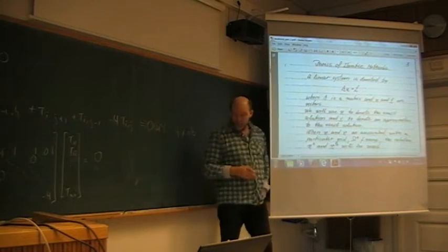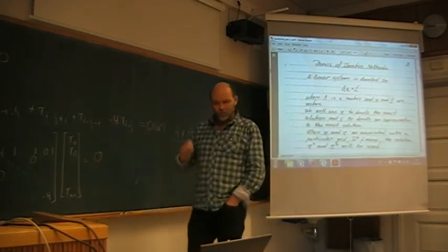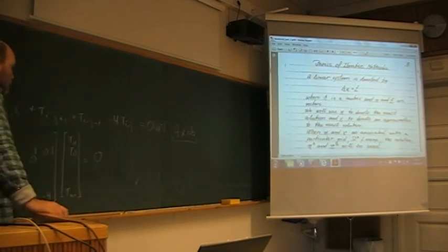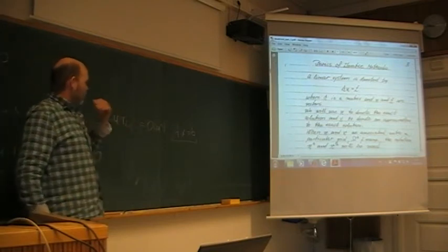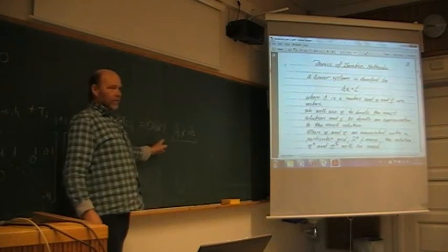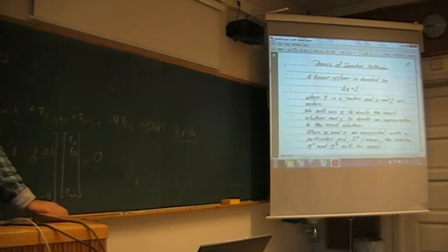It's second order accurate, or depending on your scheme, some accuracy level here. Of course, it's possible now to take this algebraic equation system and solve it perfectly, down to machine accuracy. Yes, you can do that. But why should you? Because you have an error here anyway. So when you have an error which is a little bit smaller than this error, then you should be satisfied. It doesn't help to go any further. So to solve the equation system down to machine accuracy, that's sort of a waste of time and money. Possible, but why should you? So keep this in mind.